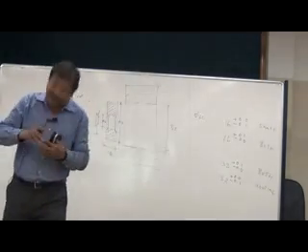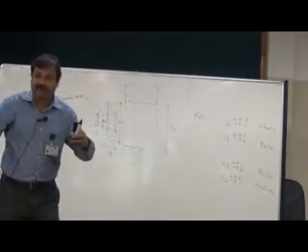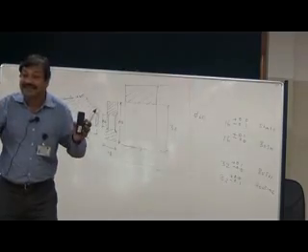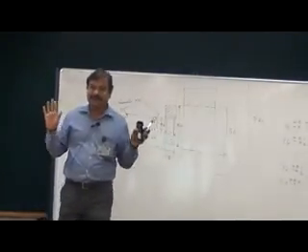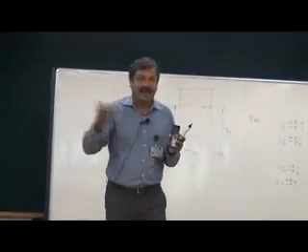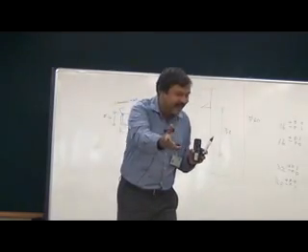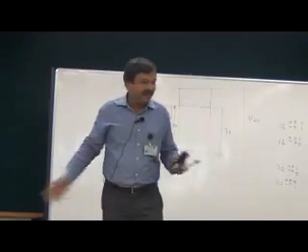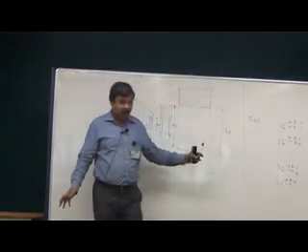When you assemble them, I may have difficulty in assembling. I may have to hit it and then push it inside. But when assembled, there won't be any relative motion between them. So by simply controlling dimensions, I am able to achieve whatever I want. If I want free running, I can have free running. If I want no relative motion, I can achieve no relative motion.